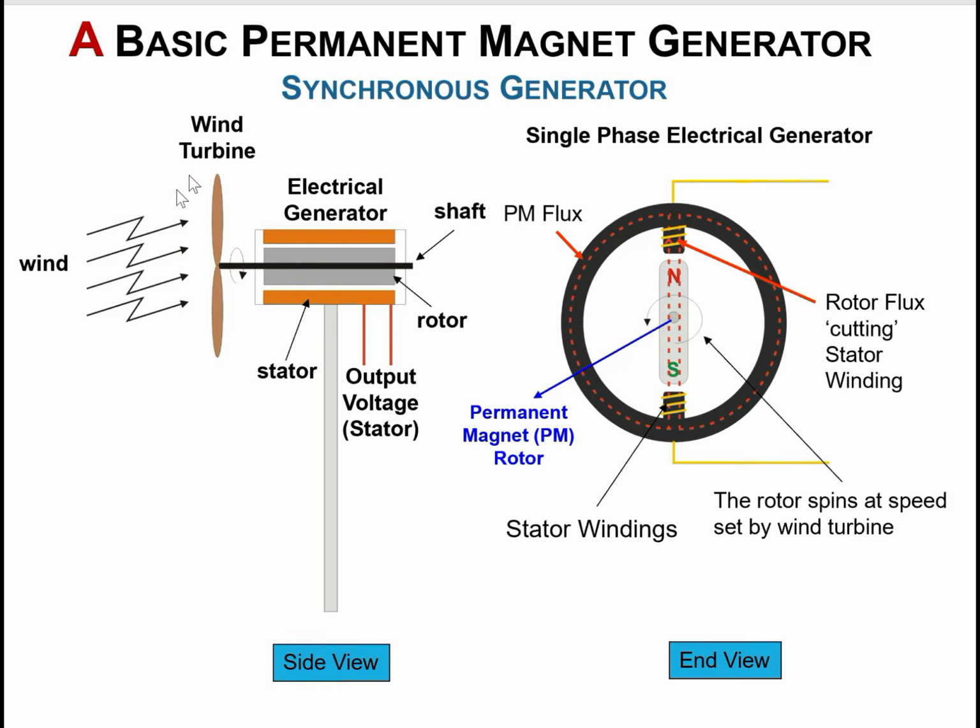So imagine here with me that the wind causes the rotor to rotate, but remember the rotor has a permanent magnet mounted on it. So as the rotor is turning, the magnetic field produced by this permanent magnet is rotating as well. And the rotating magnetic field induces voltage into the stator. And once that is induced, an induced current starts flowing into the connections of the stator, and that's why the stator can be connected to any source of load or to any type of load.